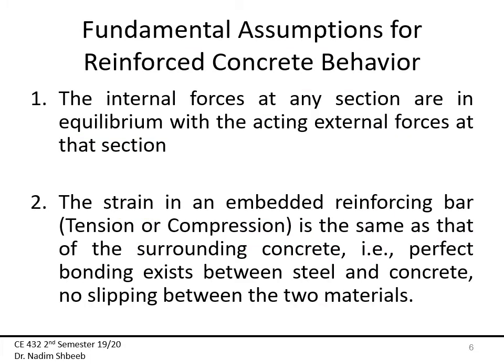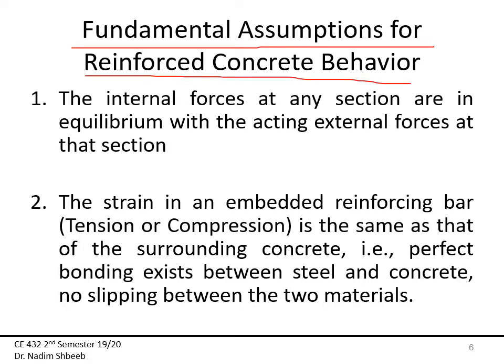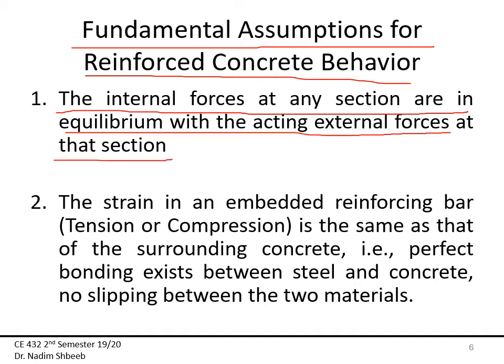Next, I'm going to talk about the fundamental assumptions for reinforced concrete behavior. And there are actually 5 assumptions. If any of these 5 assumptions are not there or are not enforced, then all that I'm going to explain to you, all the theories that I'm going to talk about in the coming slides, are pretty much worthless. So we need to understand what these assumptions are. I'm going to start with the first one, which is that the internal forces at any section are in equilibrium with the acting external forces at that section, and that's actually obvious.